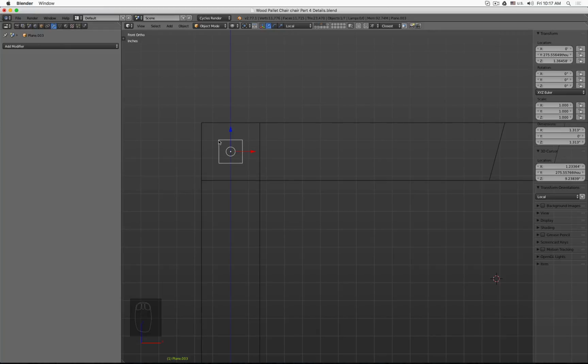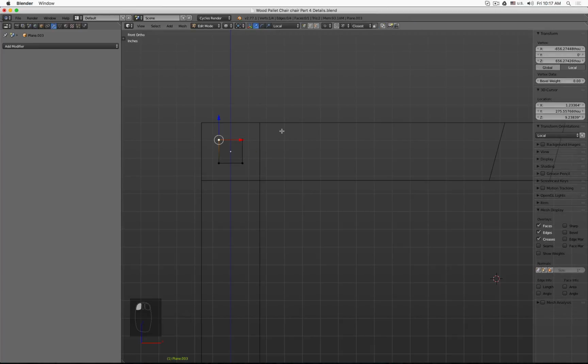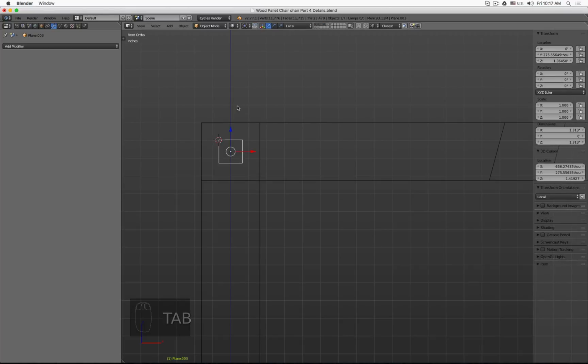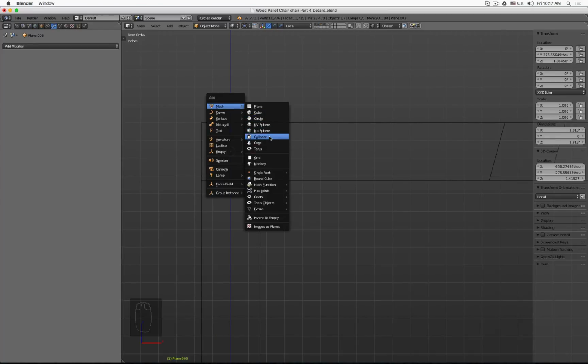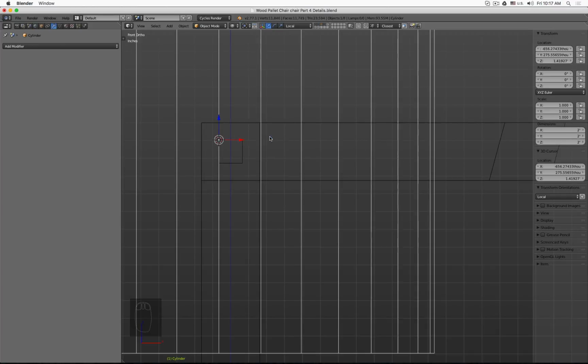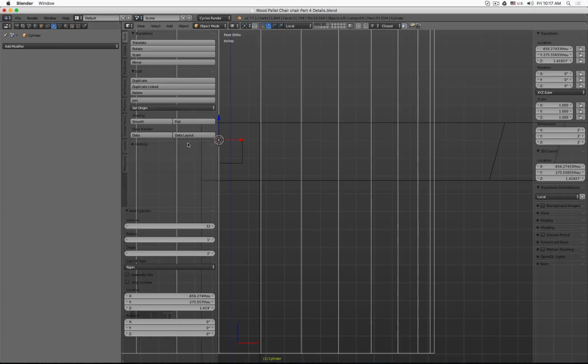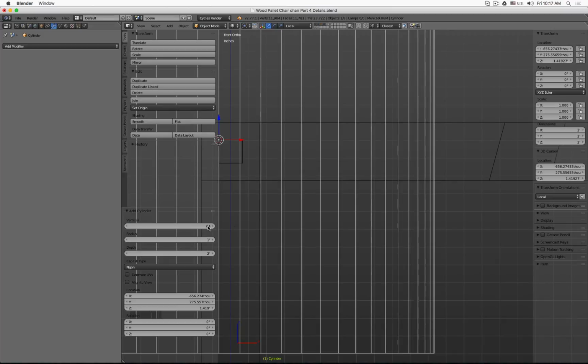And onto each point, I can, for example, position a cylinder. So click this one, cursor to select it, and then in object mode, not in edit mode, in object mode, I will Shift A, and then let's add a cylinder. Press T, so we see the amount of vertices. Let's set this to 64.